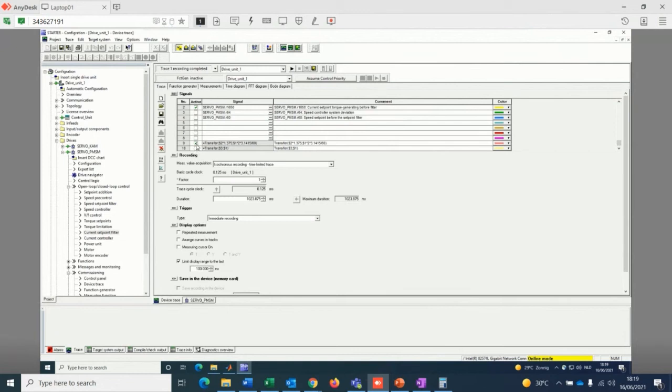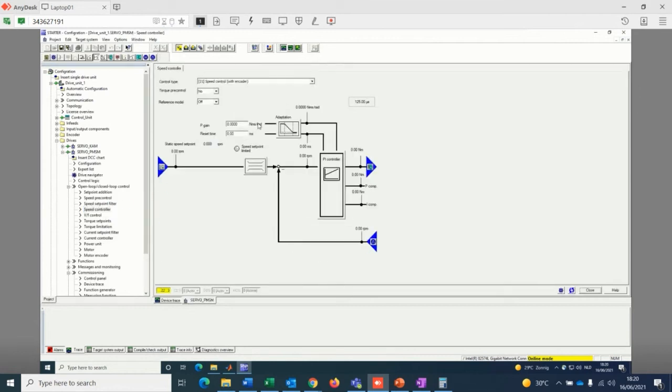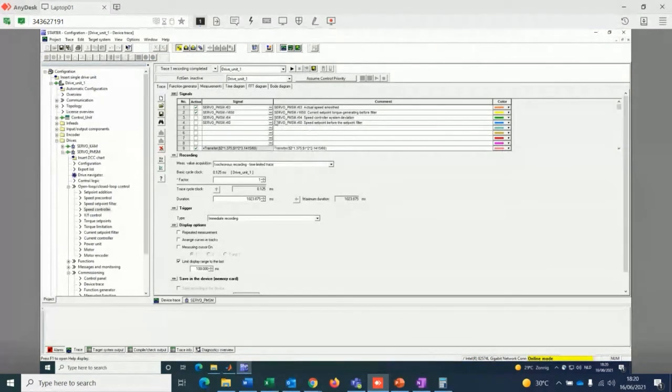The first one, the signal 9, we must tick that one. It's important to mention that this signal already has the scale that is needed for the units. As Sten explained during the presentation, the controller's units are different from the ones that we have here in the starter. We have RPMs, and the control units, as you can see here, are in Newton meter per second over radians. So we have radians per second here. So here we already scale the values.